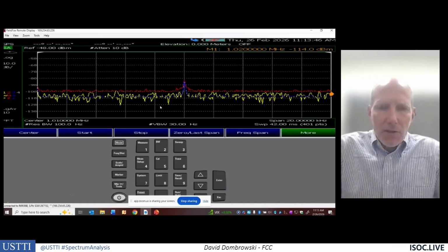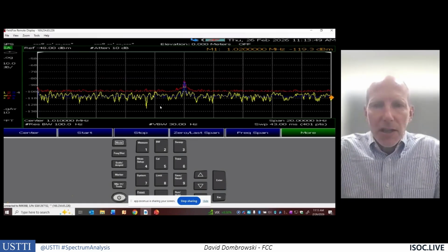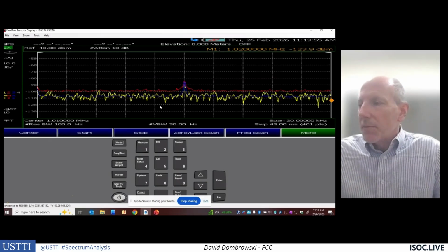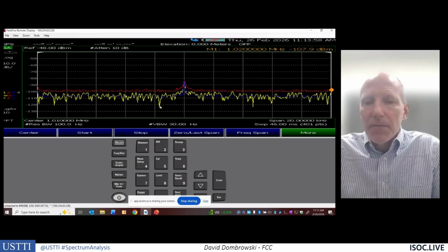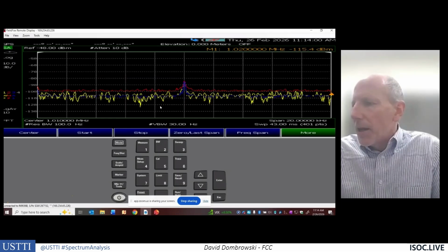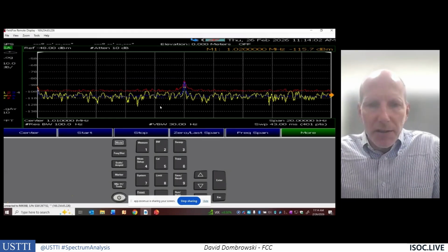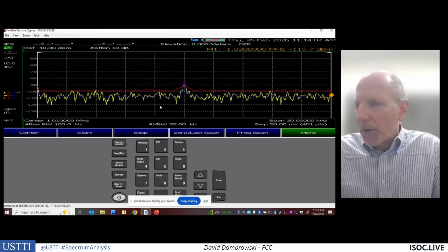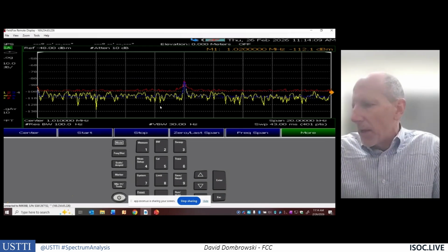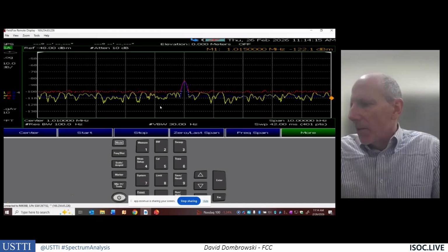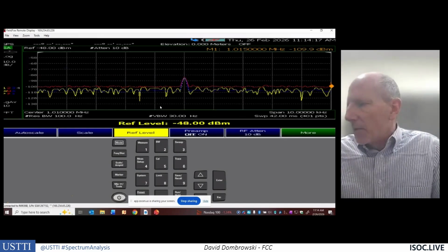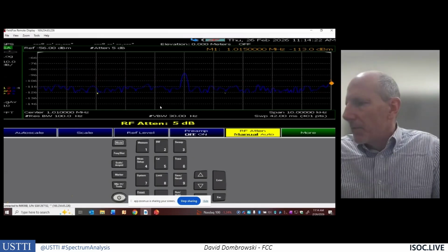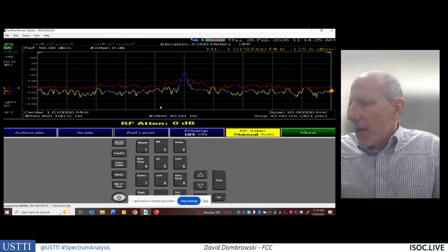And we know in amplitude modulation, the carrier doesn't change in signal level. So our first measurement is just to measure the carrier. The spectrum analyzer can be used as a frequency counter. How I do that is I zoom in on the signal of interest. I'm only looking at a span of 20 kilohertz. These signals really only occupy 10, so we can even go down to a span of 10 kilohertz. There's some modulation on that signal. Maybe I change my amplitude a little bit. So there is our signal.